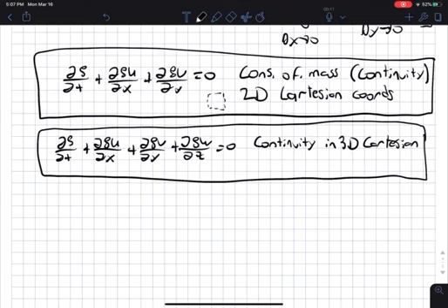Okay. And you can derive this the same way. You can use an infinitesimal control volume, but instead of looking like a square, it'll look like a cube. And you just got to keep track of everything. And it's largely the same, it's just a lot more bookkeeping. Okay? But, so what do you do about other coordinate systems? It's not uncommon that you'd want to work in cylindrical coordinate systems. Like if you're doing pipe flow, it'd be very natural to work in cylindrical coordinate systems rather than a Cartesian coordinate system. So what do you do about that?